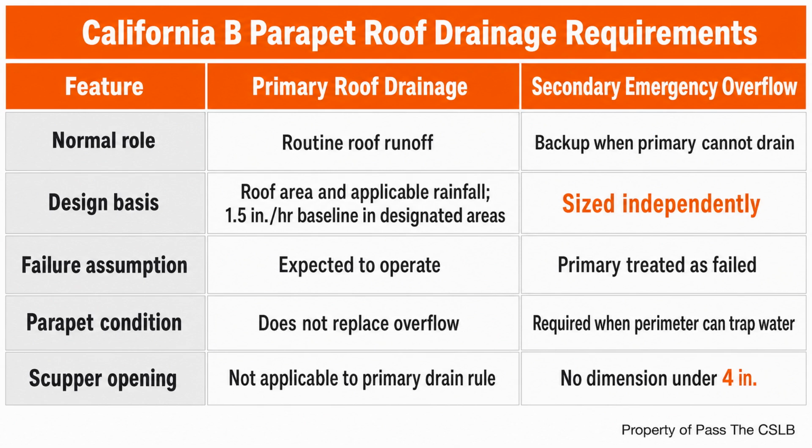For residential type framing, positive fall protection is triggered when an employee is 6 feet or more above the grade or floor level below while working on top plates, joists, rafters, trusses, beams, and similar framing surfaces. For residential type roofing, the trigger is also a fall distance of 6 feet or more. The supplied rule applies across the residential roof slope range, including low slope and steep roof work. I do not carry an outdated 15-foot residential framing habit onto a current job.